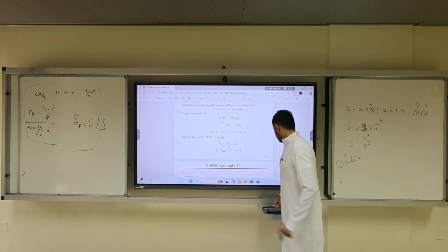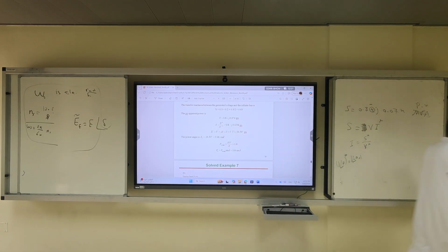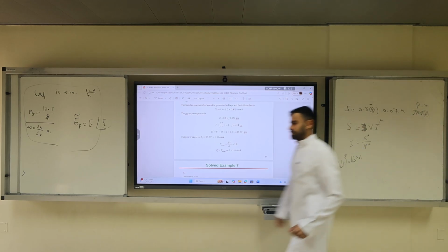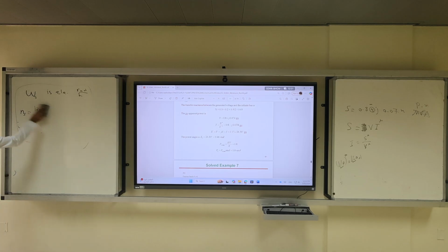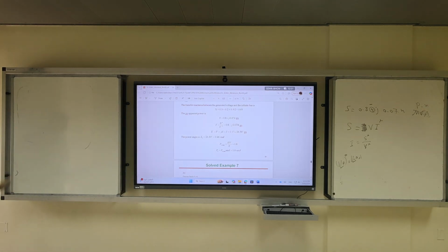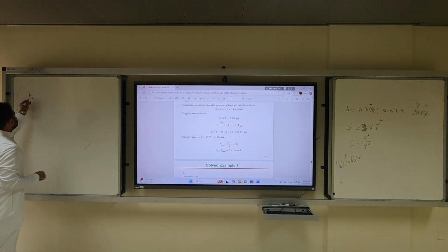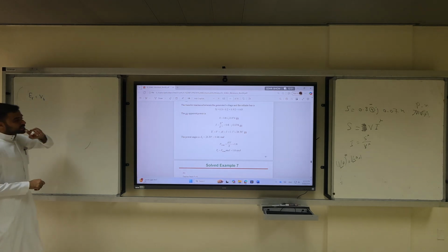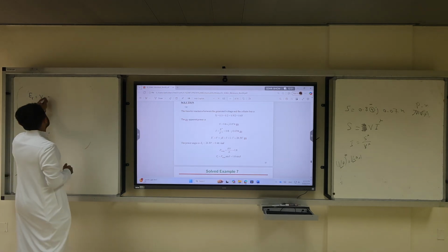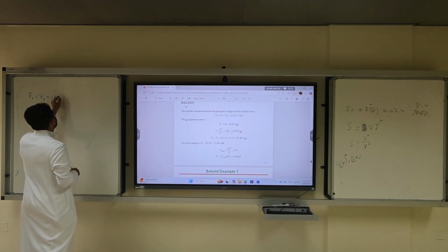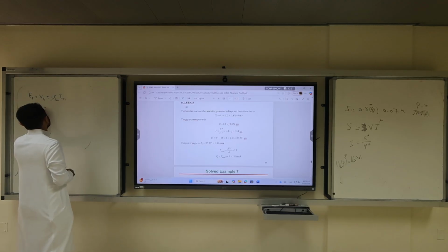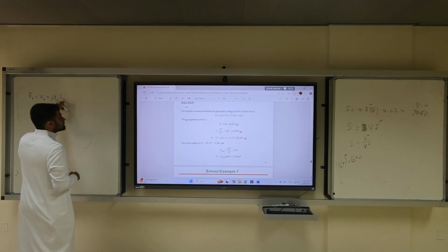So what is E? E now. EF is VT plus or minus, is this a generator? Plus. Yeah, right. Plus jX total times the current IA. So it is 1 plus jX total, what is X total? 0.65. What is IA?